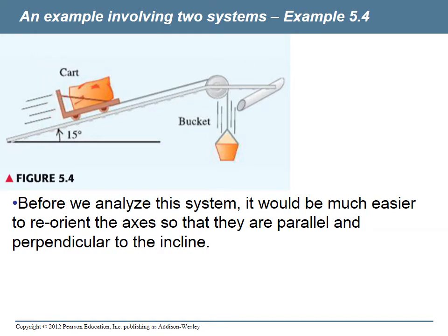This cart is not accelerating into or out of the plane whatsoever. So the summation of forces in the y direction will be equal to 0. That's why it's convenient to tilt our axes a little bit, since that makes one of those equations much easier to deal with. And then we'll have the summation of forces in the x direction, with whatever acceleration or conditions we have going on here in the parallel direction, right?